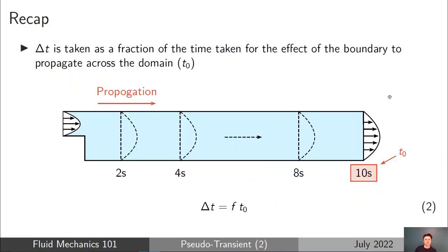And we'd like to calculate this pseudo time step automatically rather than getting the user to specify it manually, as this makes the approach more general. And the way to think about the way that we specify the pseudo time step, we can demonstrate just with a simple example of a 2D flow over a backward facing step, which you can see here.